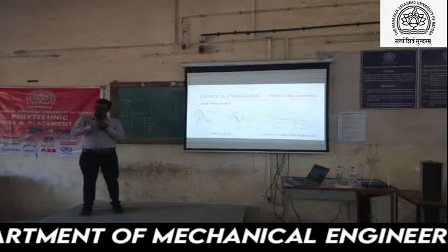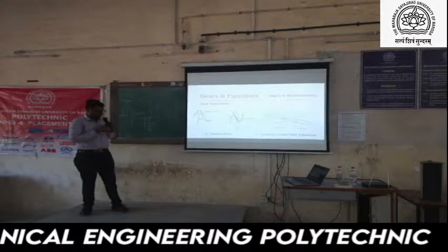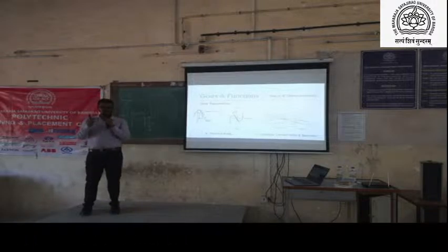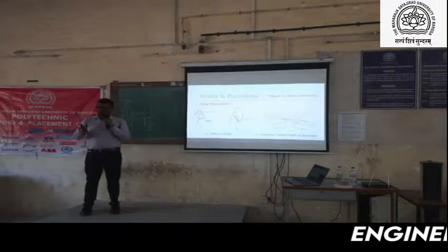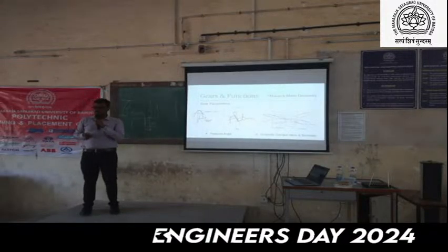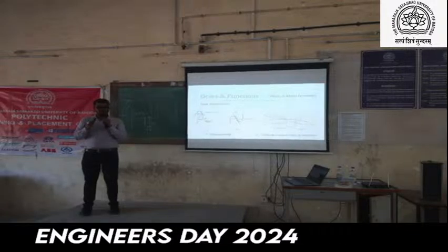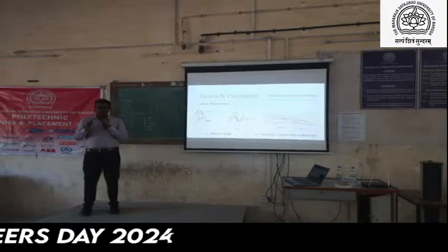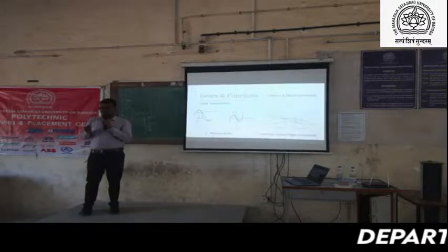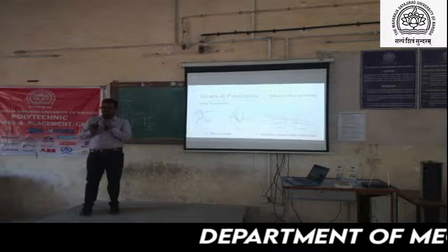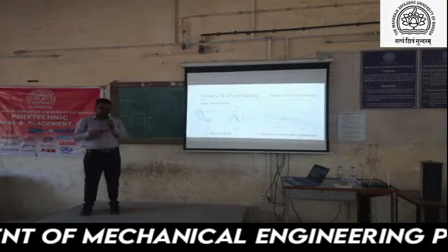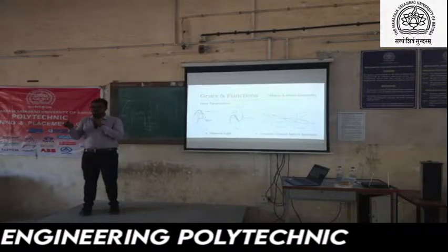Again, failure will occur if you design like that. That's why this pressure angle is used. There are lots of pressure angles like 14.5, 20, 22, 25, 30, even 30 also there. This is what I said is the standard pressure angle. In the automobile industry, they are using 14.5, 22 also. Based on the application, load carrying factors, failure, efficiency, the pressure angle will vary. So there is no thumb rule that it needs to be like this. If you vary the pressure angle, you need to invest your money in cutters.